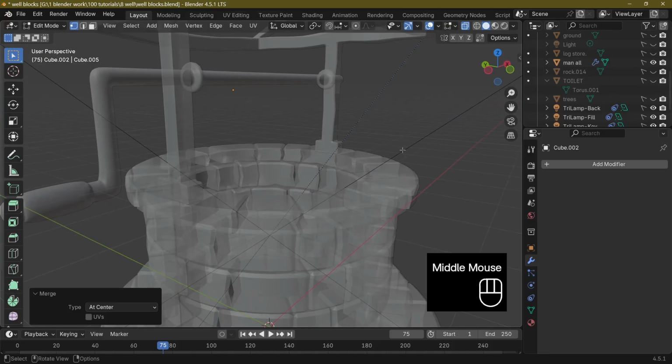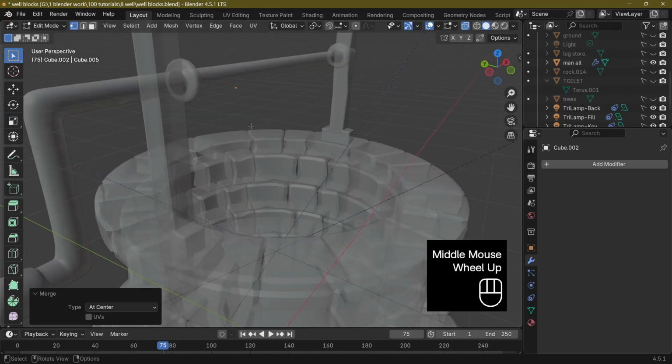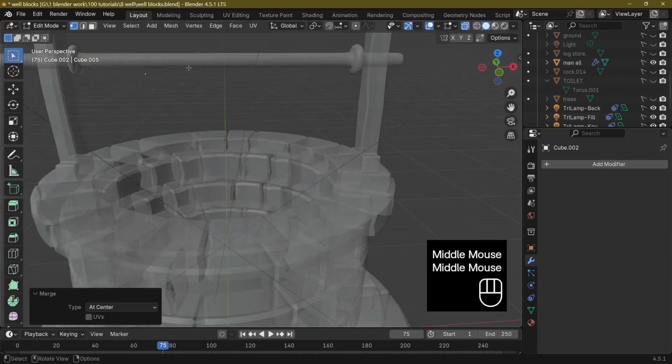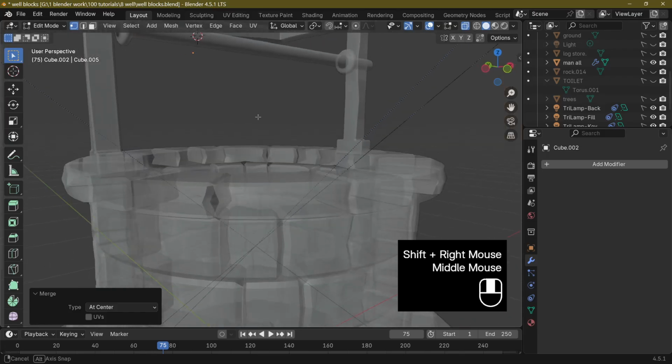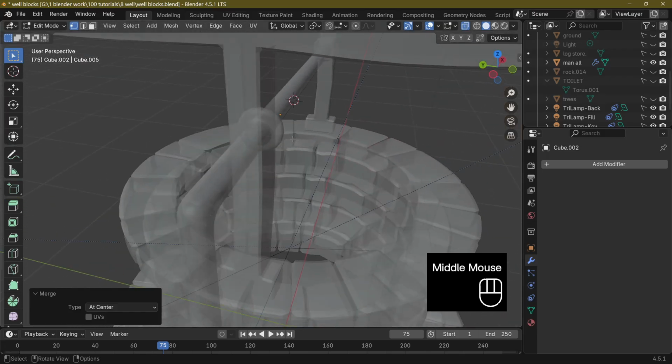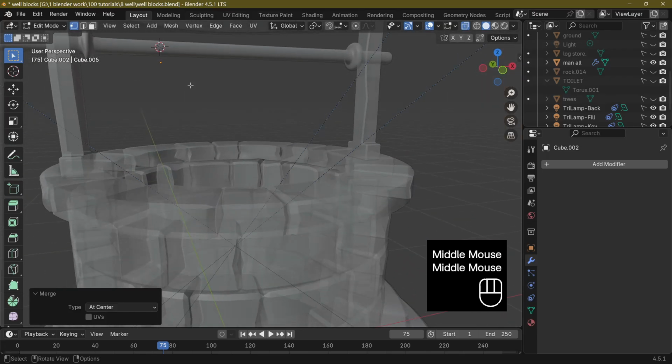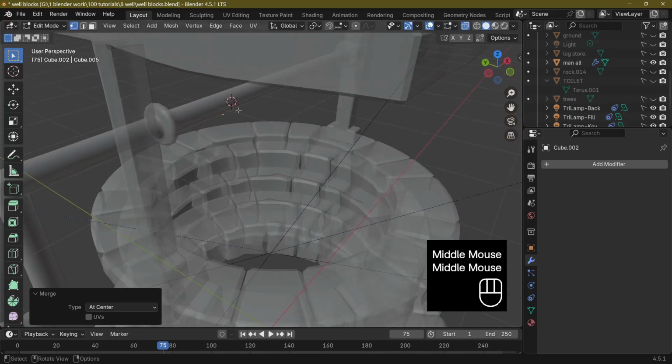So what we're going to do now is we're going to actually move our 3D cursor to the actual center of our spindle there. Press the 1 key, and we'll change it to the center of our spindle by holding the shift key down and right clicking like that. So that will enable our rope to actually go around our spindle. As you can see, it's slightly offset.